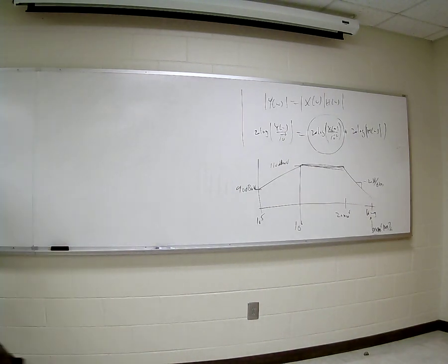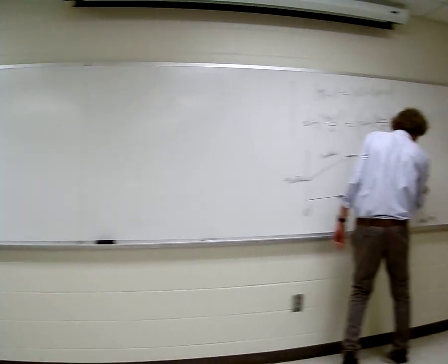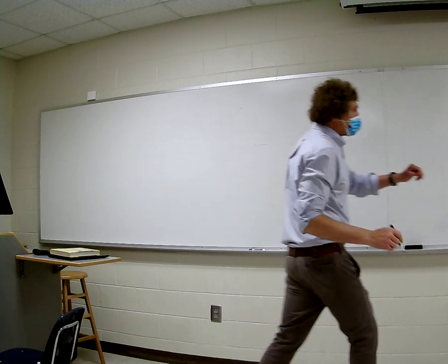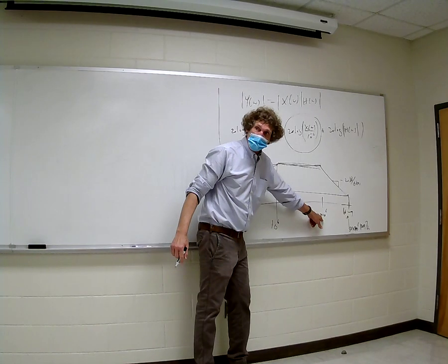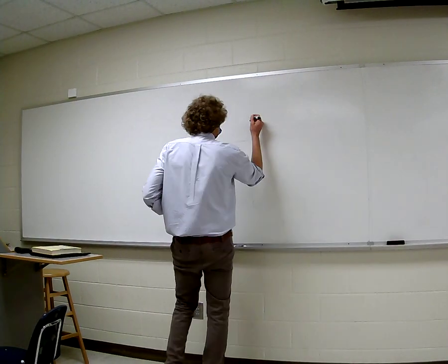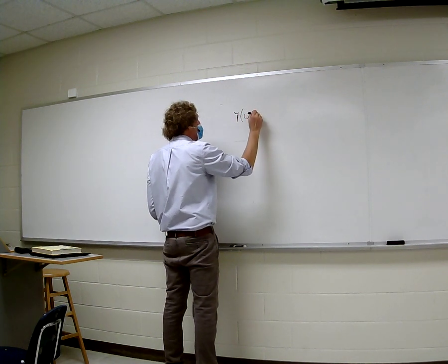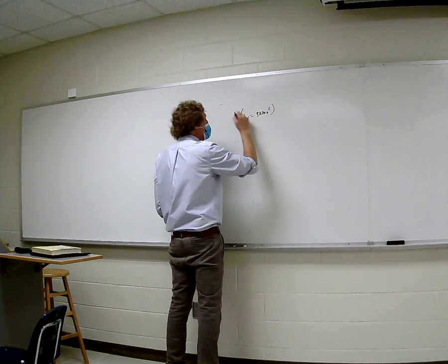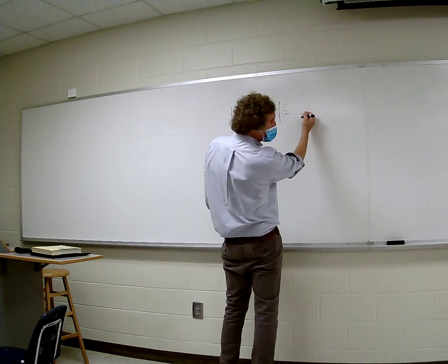So now what we end up doing, remember, I want the level of the output right out here. That's what I'm after. So I know the level of the output at 20 meg, and I know that's 110. So I say, what is Y out, Y at omega equals 50 times 10 to the 6th? The magnitude of that is going to be equal to, it starts at 110